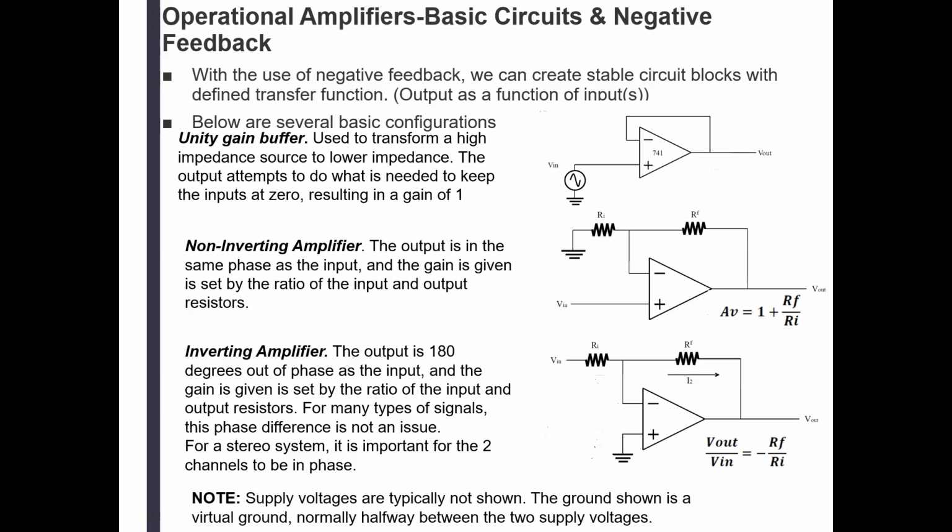So it is assumed that supply voltages are not typically shown. The ground shown is a virtual ground, normally halfway between the two supply voltages. So don't forget to connect the power. Don't call me and say, "Oh, it doesn't work. I get nothing on the output." Well, did you connect the power? That's what you're going to hear.